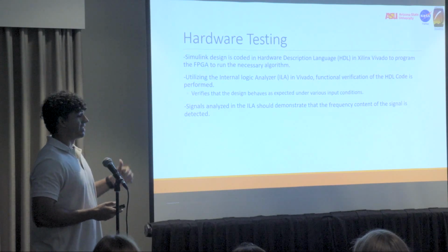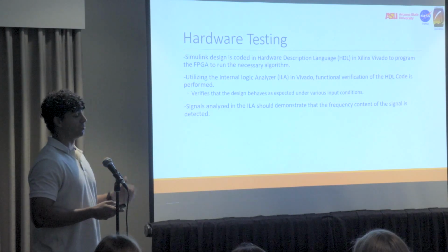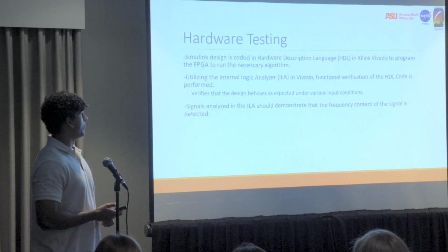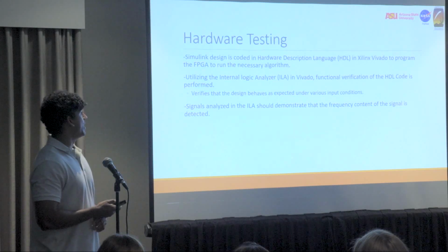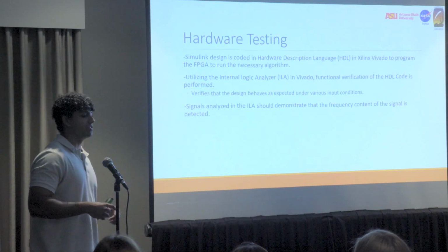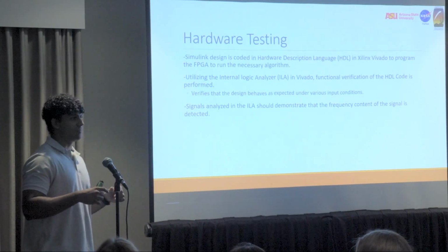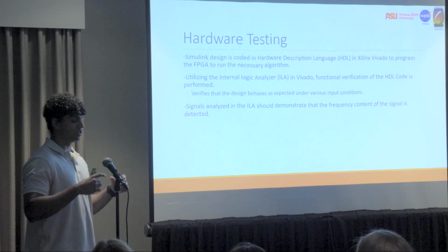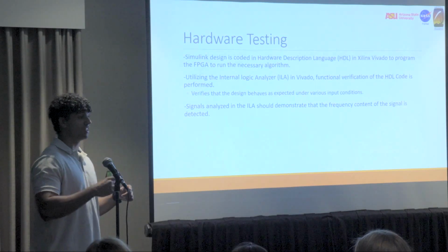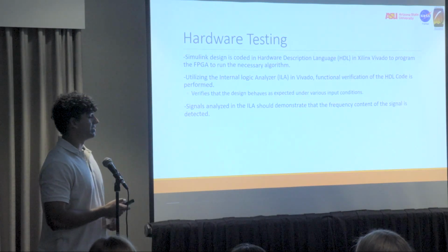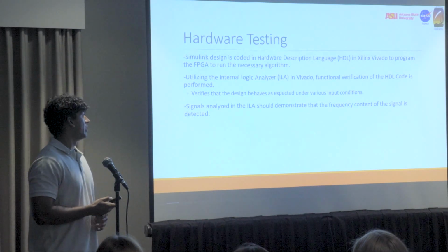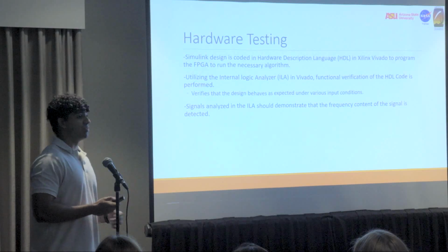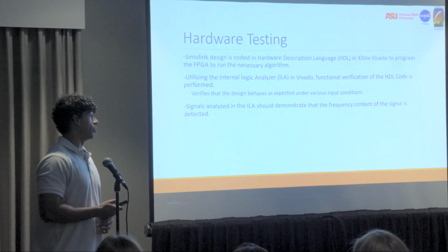And the Simulink design is then coded in the hardware description language, which is VHDL, in Xilinx Vivado to program the FPGA to run this algorithm. And then I utilize the internal logic analyzer in Vivado, as we will not be outputting this to anything yet, so you'll just want to see what the data looks like on the FPGA itself. This allows for functional verification of the HDL code when it is performed. And the signals analyzed should demonstrate that the digital spectrometer works.